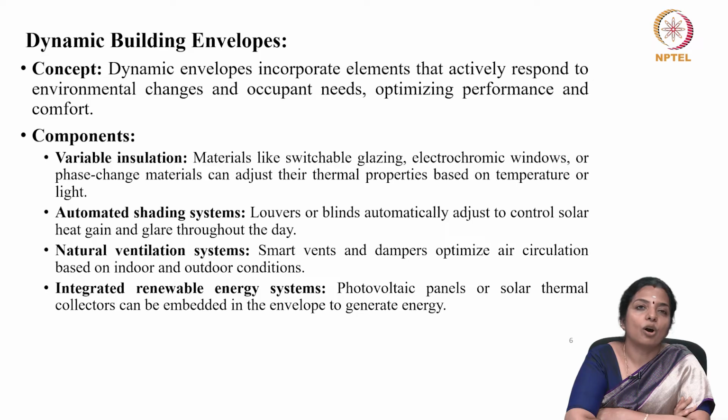You can have automated shading systems. That is, you can have shading devices, which could be louvers or vertical fins or blinds, which will automatically change as a response to the outdoor solar heat gain or glare.